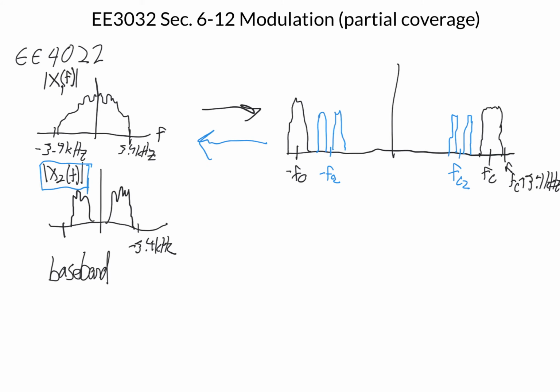So in order to design circuits to do this, we need to understand where the frequency content of our signal is, and the Fourier transform and also the Fourier series are going to help us look at signals that way, so that we can share the bandwidth of whatever medium we are transmitting one or more of those signals over. The simplest approach to moving a signal up, or modulating it to a higher frequency, is called switching modulation.